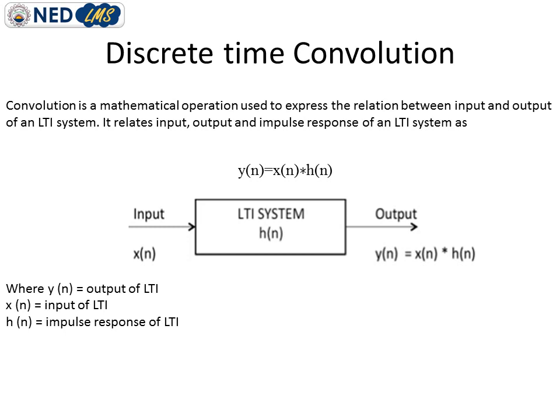Thirdly, the overall output signal can be formulated by adding these scaled and shifted impulse responses. In other words, if we know the system's impulse response, then we can calculate what the output will be for any input signal. This means we know everything about the system. Whatever the input, we can determine the output if we know the impulse response.